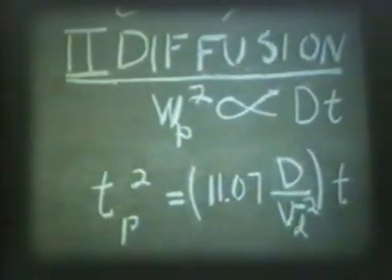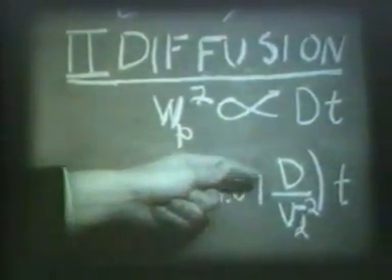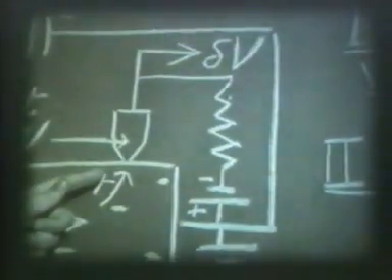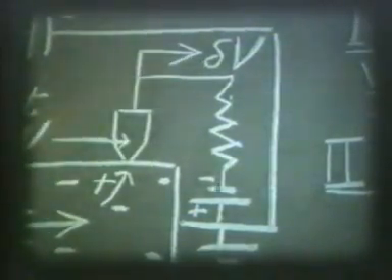In order to use this equation to test diffusion theory and to measure D, Dick Haynes must first show that the hole concentration at the detector is proportional to the scope deflection delta V. The deflection is proportional to the concentration of holes under the detector point. Many other experiments show that such linearity is a property of a reverse biased detector rectifier. You will understand more about the reasons for this when you study PN junctions. However, we can make a linearity check here.